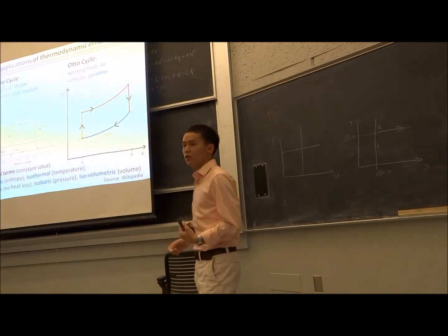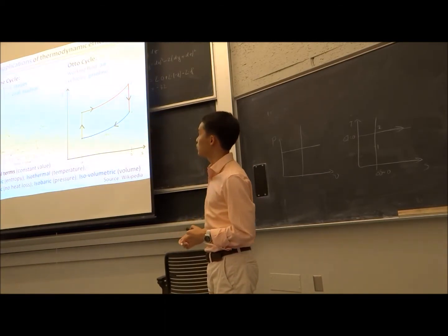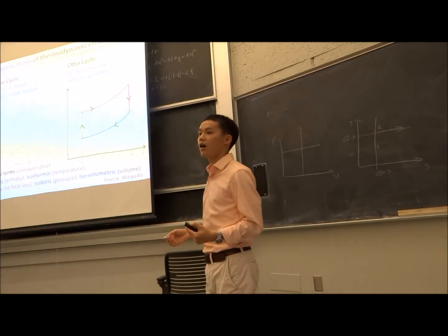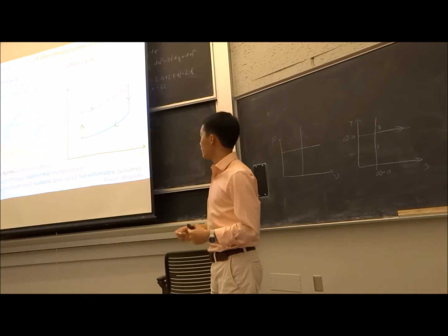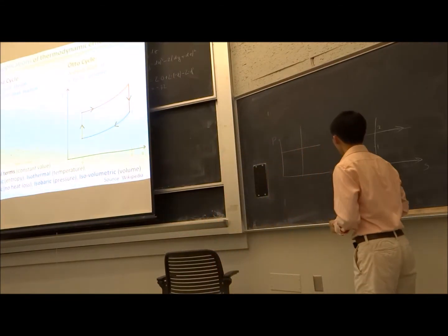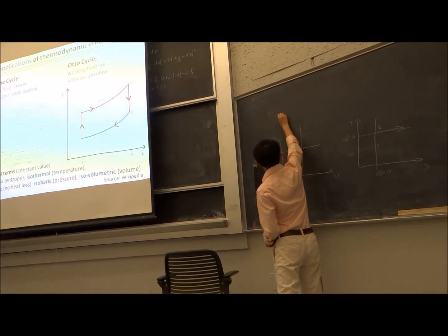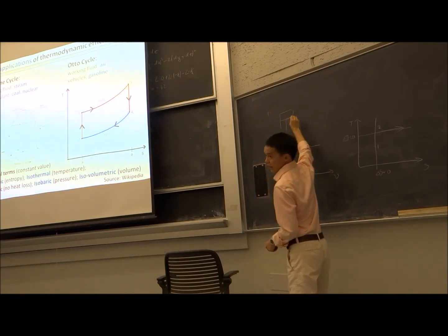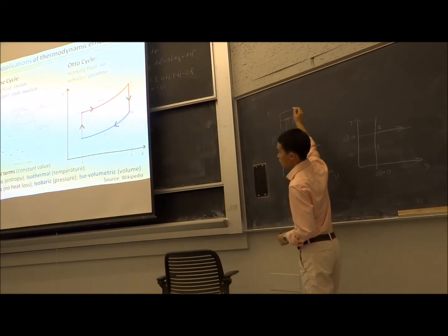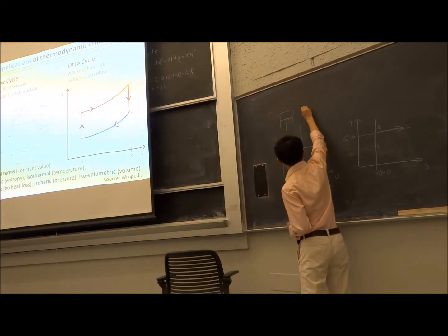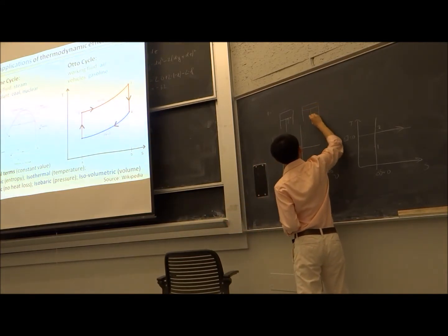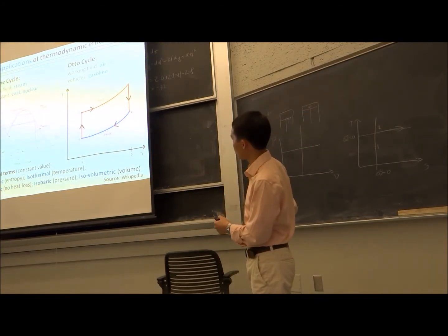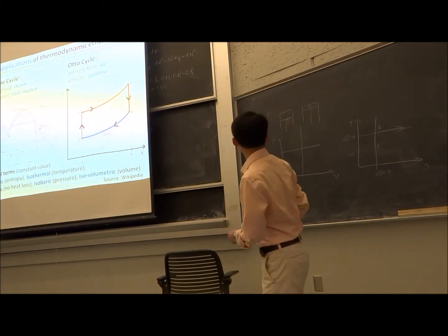This Otto cycle is simpler. It deals with air. It does not deal with water. So the typical application we can think about is a gasoline car for the Otto cycle. In the class, we'll draw this, right? For the Otto cycle, the process is that you have the piston and cylinder. The first process is that it compresses the air to a smaller volume, and then ignites the air and fuel mixture over here in a constant volume process as 3.